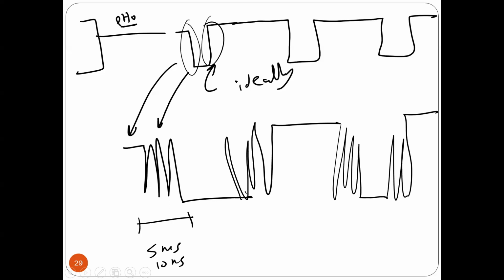Is that okay? Again, what I'm saying is this is ideally, but in reality, because of the mechanical parts and the spring, you are going to get a signal like this one, because connect to disconnect happens for just 5 milliseconds. So for sure, I cannot say that you pressed 3-4 times here. I cannot say that because there is no human being that can press 3-4 times in 5 milliseconds. You cannot do that, right? This is just because of the mechanics. So I'm not going to be confused. That's what we call bouncing